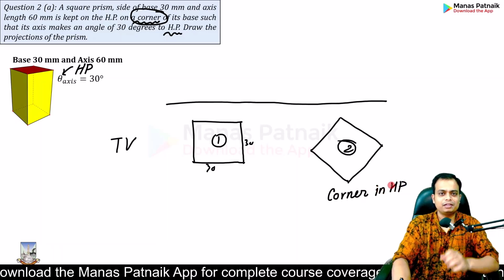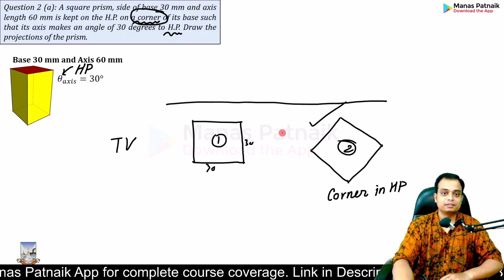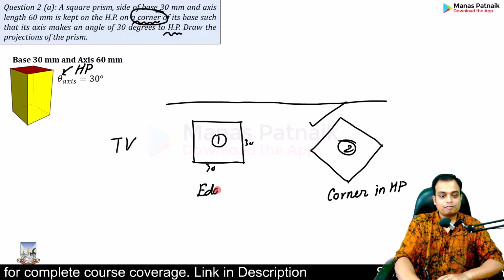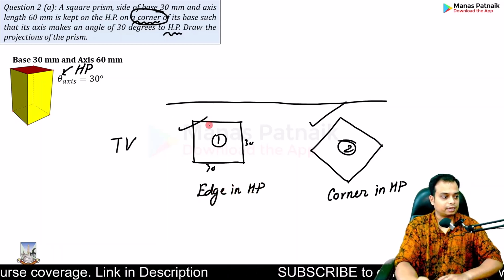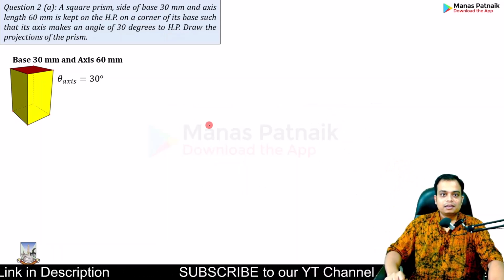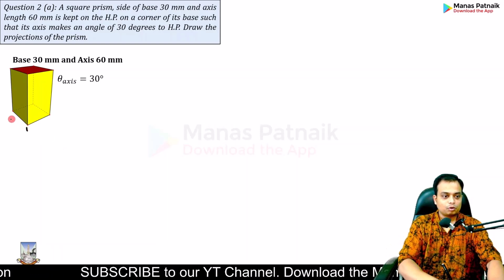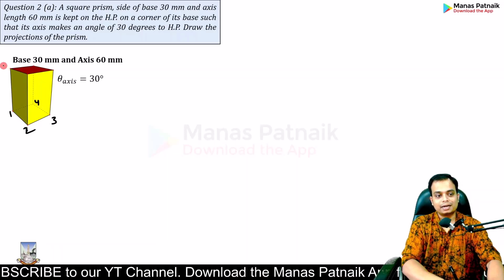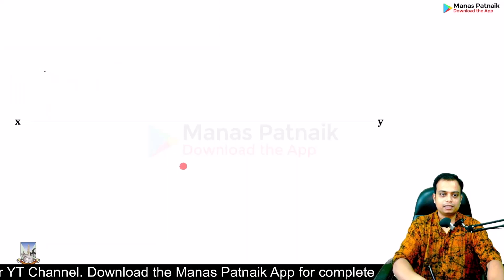Please remember, this is a very, very useful trick. If the corner is in HP, you have to start with this diagram as the top view. If one of the edges is in HP, you have to start with this diagram as the top view. So with that being said, now let's kick off with the main solution. Please remember, the bottom four corners are 1, 2, 3, 4. The top four corners are A, B, C, D. Here we go, let's start.